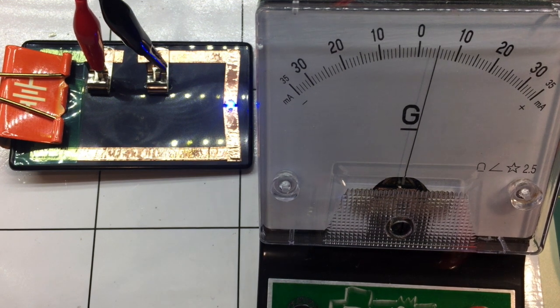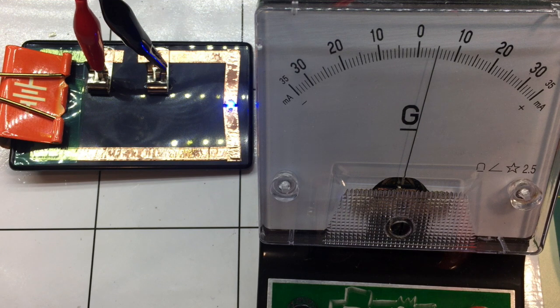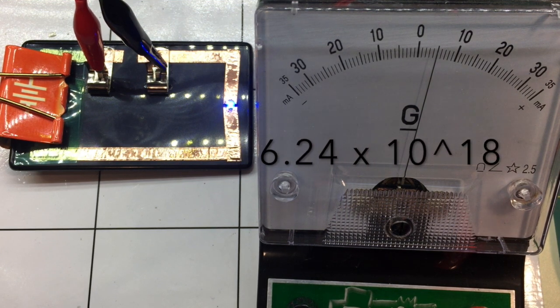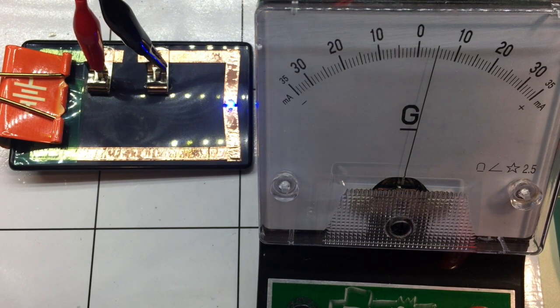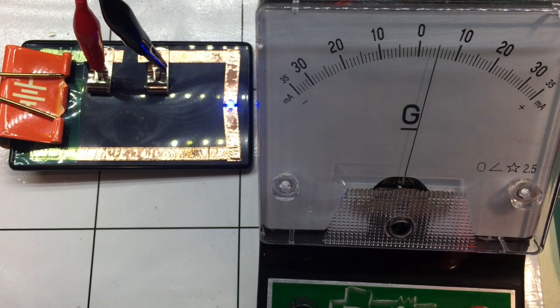So what's an amp? An amp is much more concrete. There's a particular large number called a coulomb, and if that many electrons are flowing past a particular point in a second, that means that's 1 amp of current flowing. What you want to keep in mind is, in a circuit, if you're going to measure voltage, it's always relative from point A to point B. Current is always in a line.